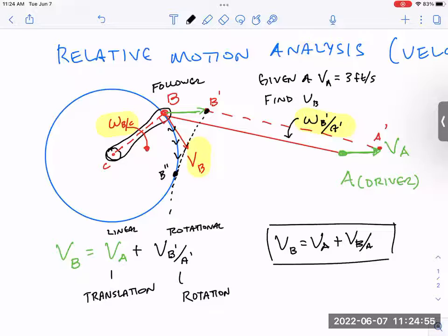And those highlighted calculations are what we're going to want to be able to understand. As I said, the most important one is probably this angular speed over here, because that's the thing that directly ends up connected to the car. I don't know that we super care exactly what the velocity of B is, but because of the formulas we have, we're going to need the velocity of B in order to find that. And this formula right here is telling us how we're going to get the velocity of B. It's not our final answer, but we can calculate it based on this logic right here. Then we'll convert it to that angular speed. So we're saying, how does this linear speed over here create angular speed over here? That's kind of cool.